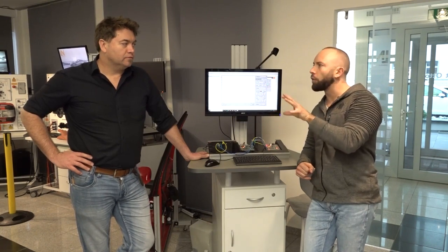you can't do anything without a circuit diagram of the nodes. You need to know where the nodes are, and it's like a town map which you need, so that you know where you are and where you measure, because without this you won't get any idea what's going on in the car. So just make sure when you're on the real car that you definitely have the circuit diagram of the CAN bus in your hands, like I said, like a map, so that you know where you are in the car right now and where you measure.